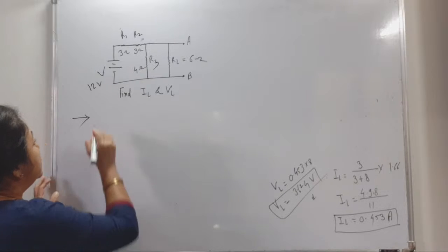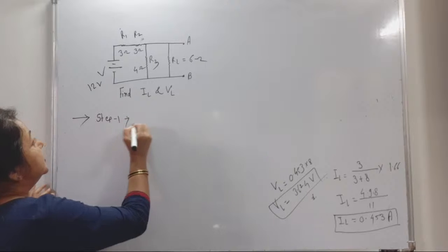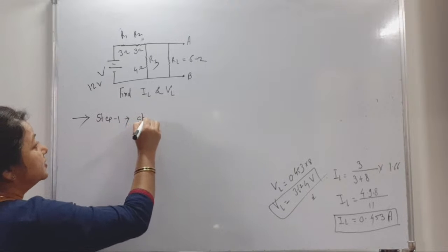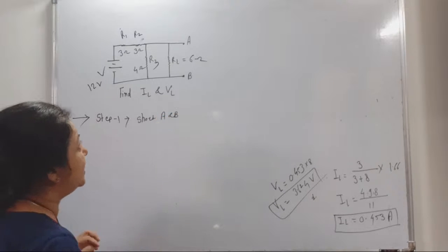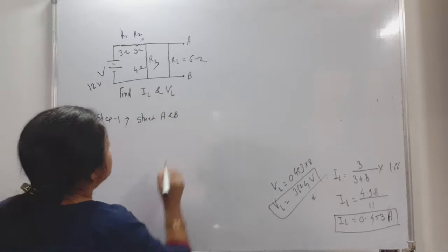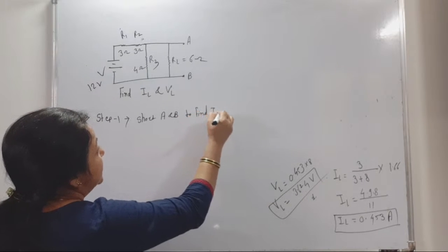So, what is the first step? Listen carefully. Step 1: short the terminals A and B to find IN.